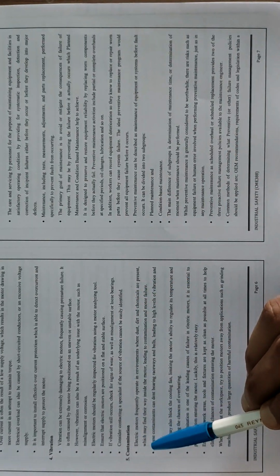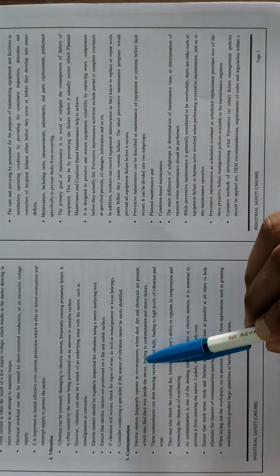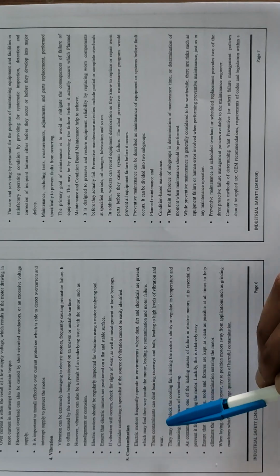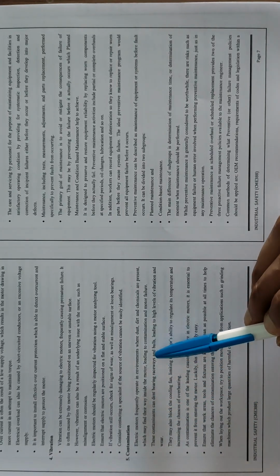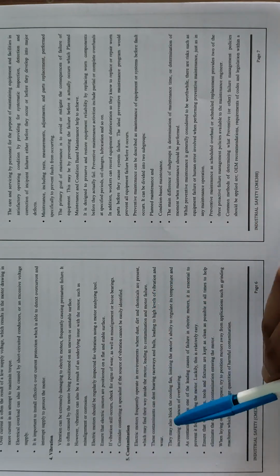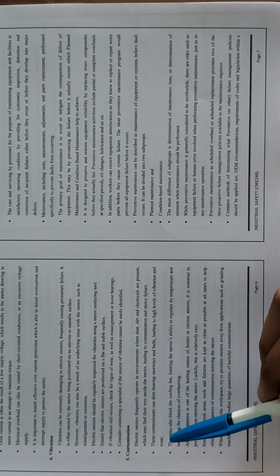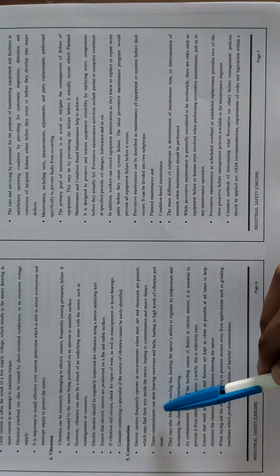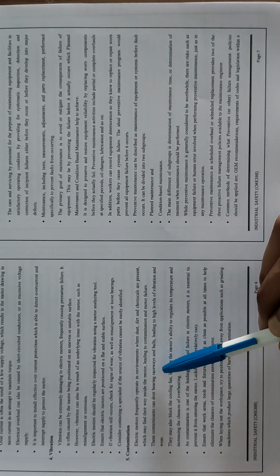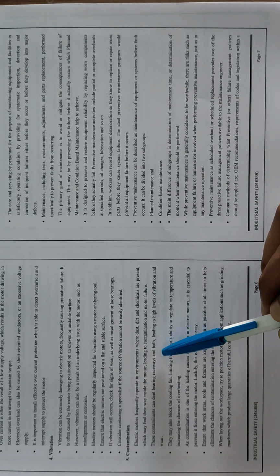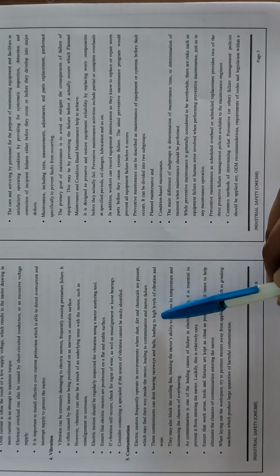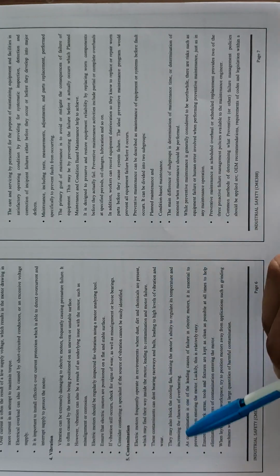Contamination. Electric motors frequently operate in environments where dust, dirt, and chemicals are present, which may find their way inside the motor, leading to contamination and motor failure. These contaminants can dent bearings, raceways, and balls, leading to high levels of vibration and wear.